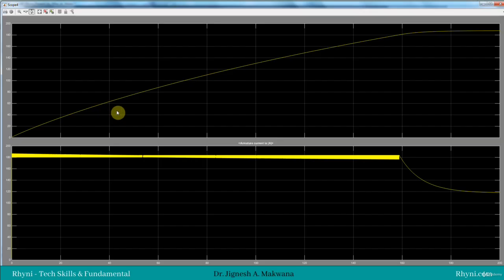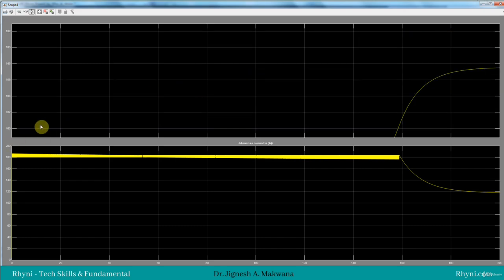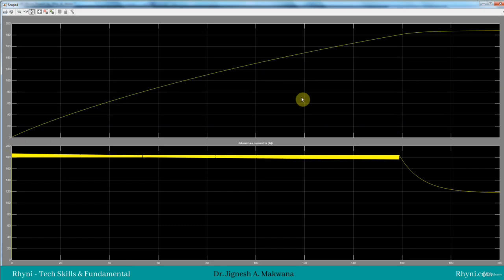So when we use the DC shunt motor, we are not getting the high starting torque and high acceleration as we get in case of DC series motor or the BLDC or SRM. So this is the issue with the DC shunt motor, and this motor is also not purposefully built for EV application, but it has 240 volt and 182 is rated current. So here you can see current is reducing to the rated current and we are reaching more than 180 km per hour speed, but the only issue is the starting response. So acceleration is slow, otherwise you can use it.